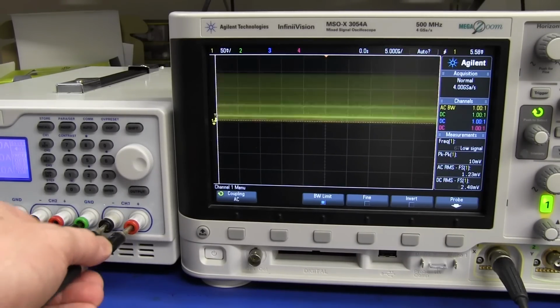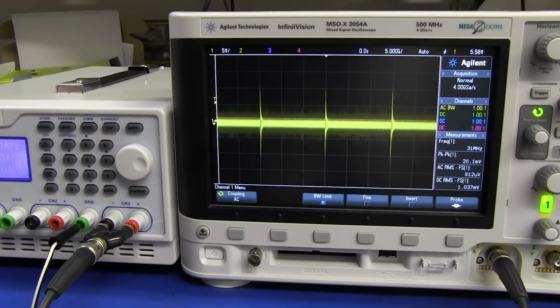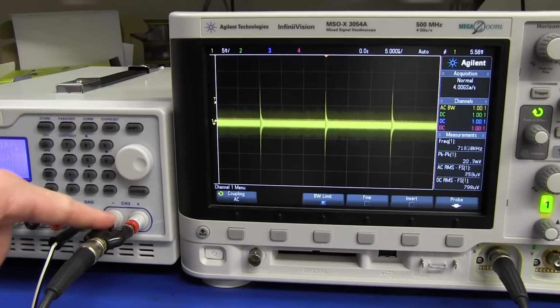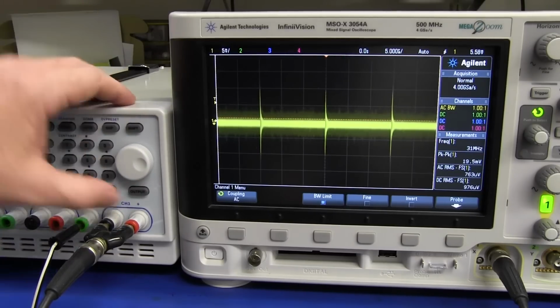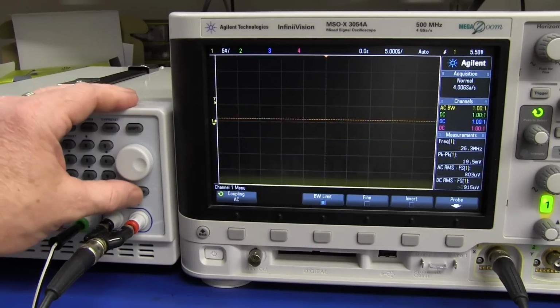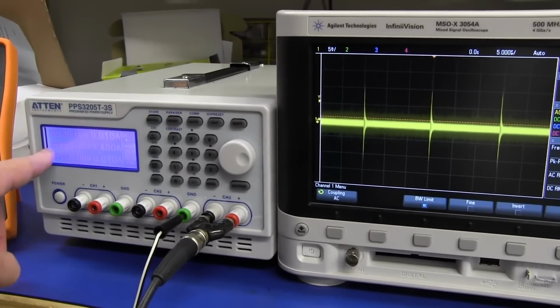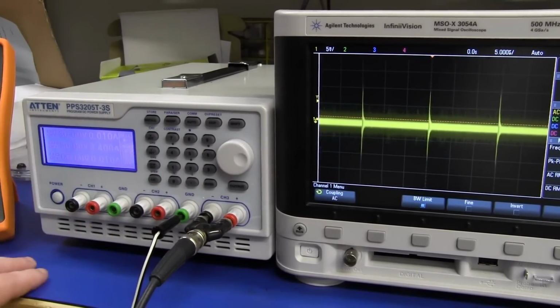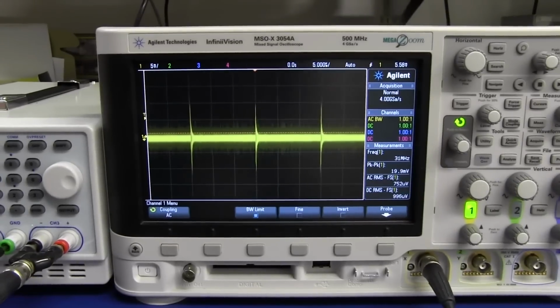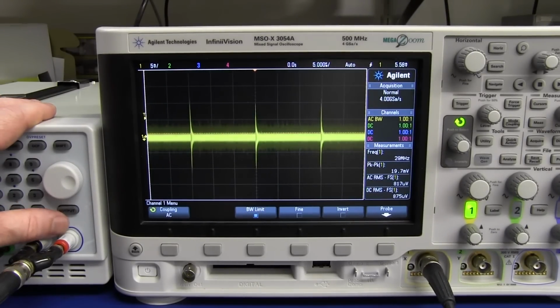So you still might think, okay, this power supply is the culprit, but let's switch the output off, okay? So the relay should disconnect the output there. So, switch all of the outputs off. There we go. Our outputs are physically disconnected. It's switched off and it's disconnected those outputs, but it's still there. You'll notice that the noise really doesn't change much at all, whether or not you've got that output on or off.